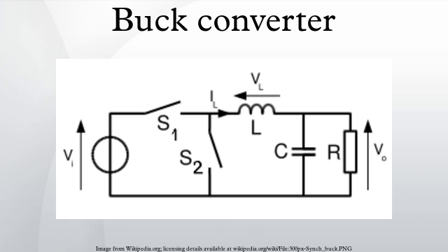In a standard buck converter, the flyback diode turns on on its own, shortly after the switch turns off, as a result of the rising voltage across the diode. This voltage drop across the diode results in a power loss which is equal to Vd times IO times (1 - D), where Vd is the voltage drop across the diode at the load current IO, D is the duty cycle, and IO is the load current. By replacing diode D with switch S2, which is advantageously selected for low losses, the converter efficiency can be improved.